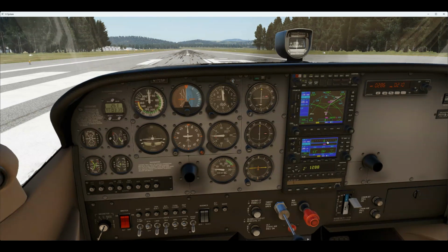applicable. Normally, some of these GPSs, by the way, I've got two of them, will dual them up. So if your flight plans up here, sometimes they don't. You can set up different flight plans depending on what you're doing. And this message is basically telling me dial this OBS here onto 172. So that message will disappear as soon as I dial it on approach.